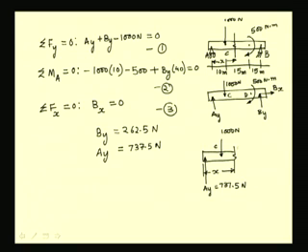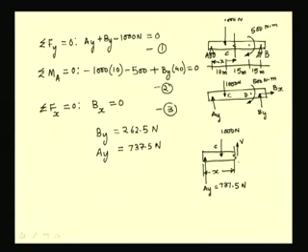The resultant of the internal forces at this section will be the shear force. Since there is no horizontal force, the axial force is 0. Even if you consider the axial force from the free body diagram, it will turn out to be 0, and we consider the moment m. Both have been taken in the positive sense as discussed.